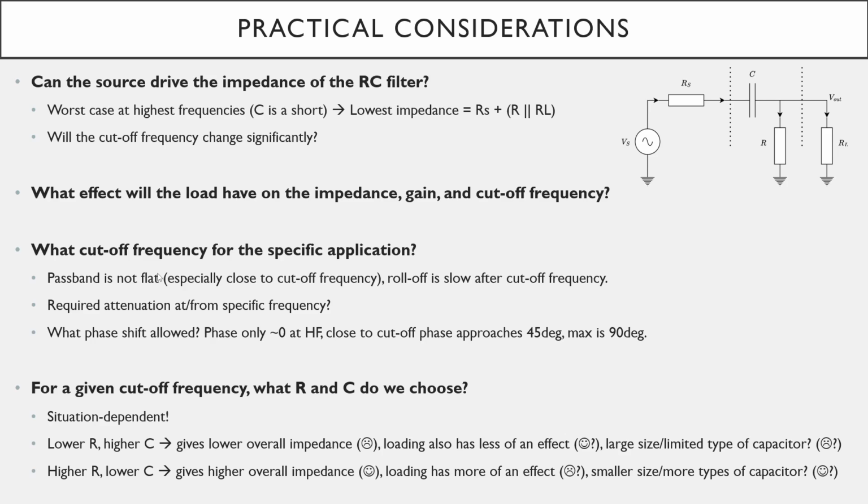You also have to consider not just the gain, but also the phase shift. If you're doing very particular measurements, or you have somewhere where phase is critical, you want to stay away from the cutoff frequency and be well into the passband to ensure that you have close to a 0-degree phase shift at high frequencies.